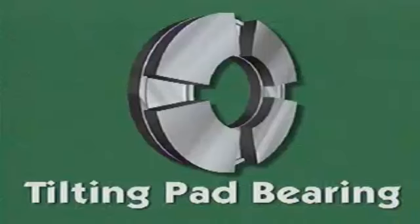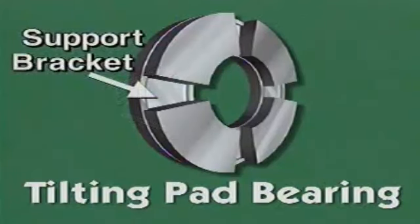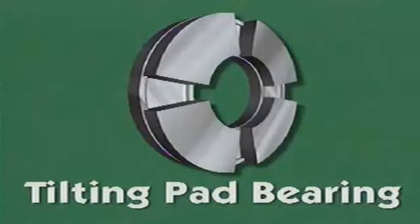This bearing is a tilting pad thrust bearing. It's also called a Kingsbury thrust bearing. A typical tilting pad bearing has two main parts: movable thrust shoes and a support bracket. The thrust shoes are pivoted to allow them to move slightly. The thrust shoes rest on the support bracket. They're held in place by pins on the support bracket that fit into holes on the back of the thrust shoes.